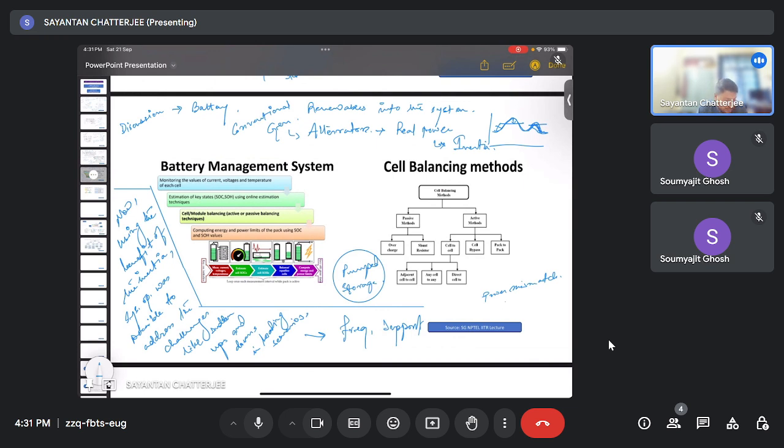Thus, what we can say, we also need a similar fashion or similar equipment that can provide at least real power support, so that the power mismatches which lead to frequency instability can be limited. Okay, so that leads to the foundation of implementing batteries into the system.